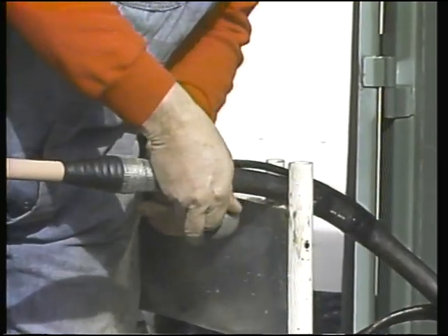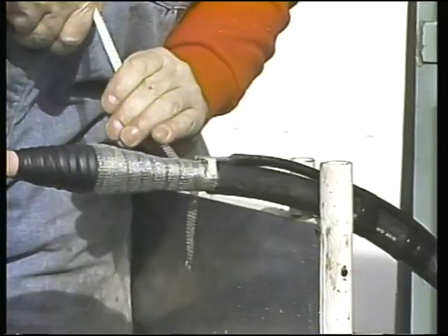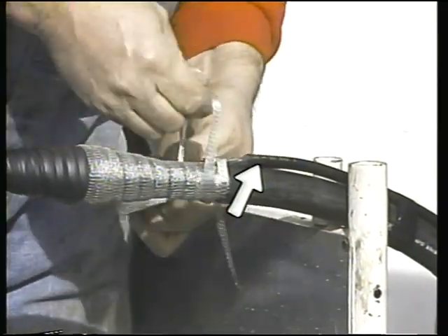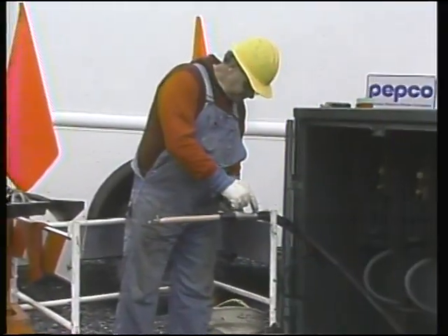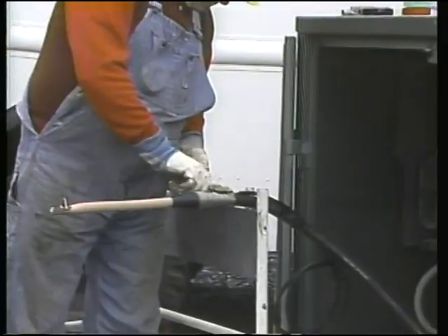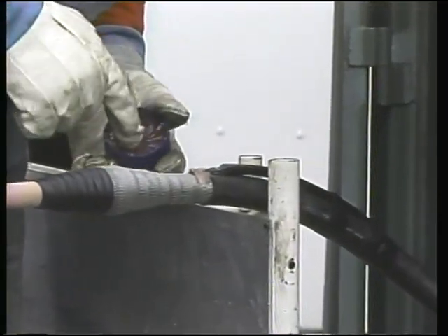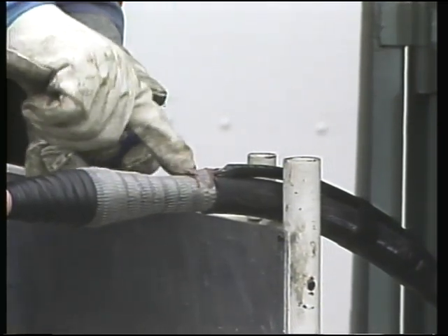After the metallic tape has been applied, the metallic shield has to be grounded. To ground the metallic shield at the termination point, an additional wire has to be attached to the shield and then connected to an electrical ground. When this connection is made, it's a common practice to join the conductive tape to the shield using solder. The solder uses a chemical agent called flux to help the metals adhere to each other.